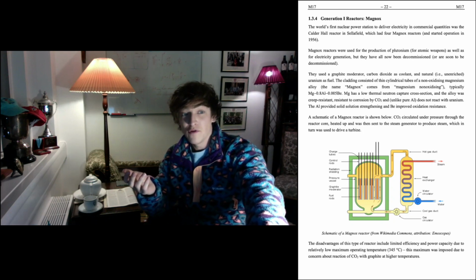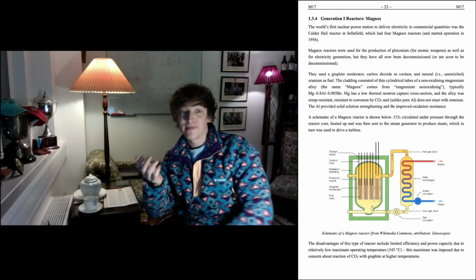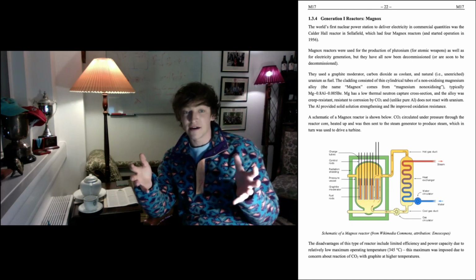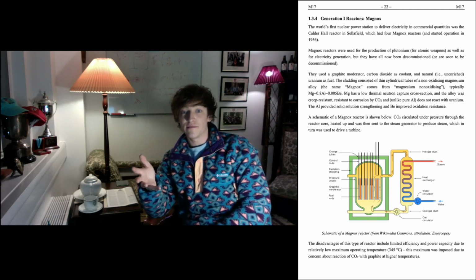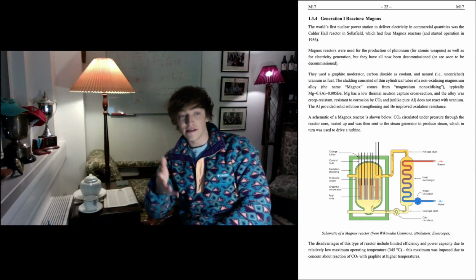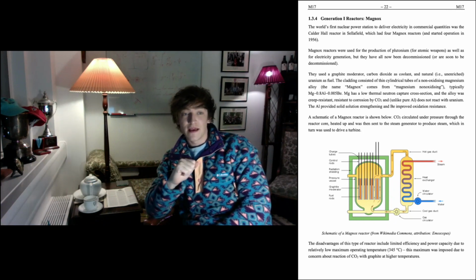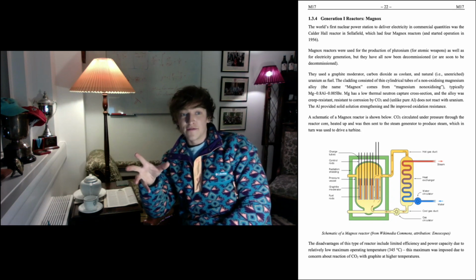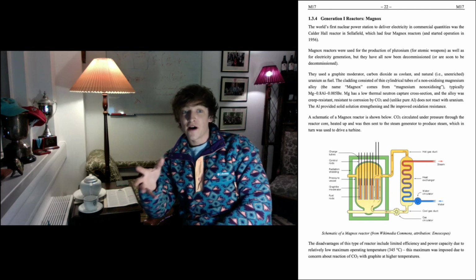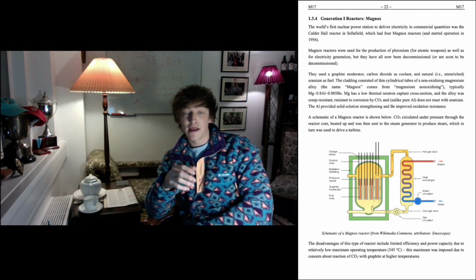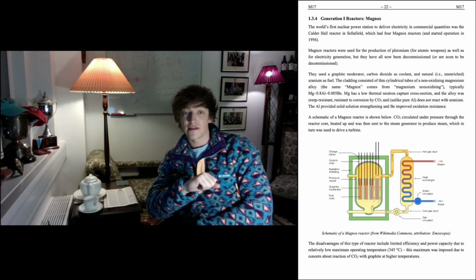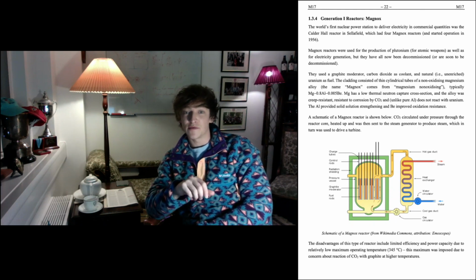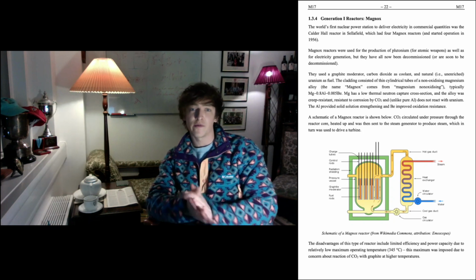Because one way of moving control rods is with electromagnets. So should you lose all power, those magnets will demagnetize and no longer hold the control rods in place. So the rods would fall into the reactor by gravity. There are alternative ways of entering control rods. They can be fired in using a pressurized gas system, and I'll show you that for the advanced gas reactors. And that just ensures they shut down their reactions as quickly as possible. So that's a big advantage. You want those control rods to be fired in.